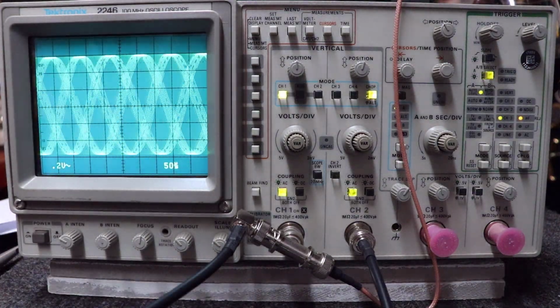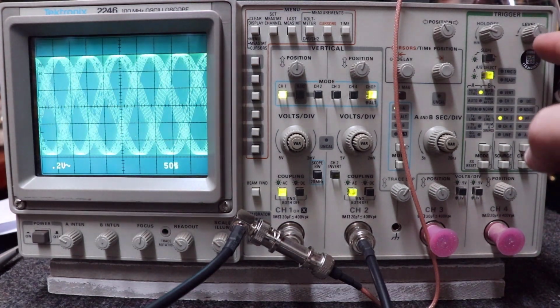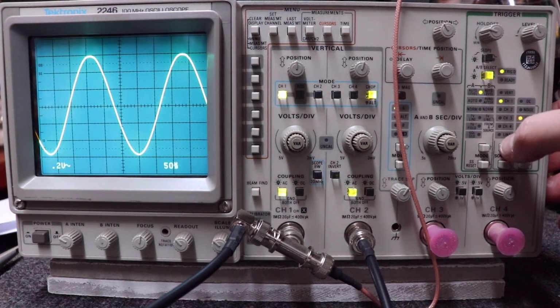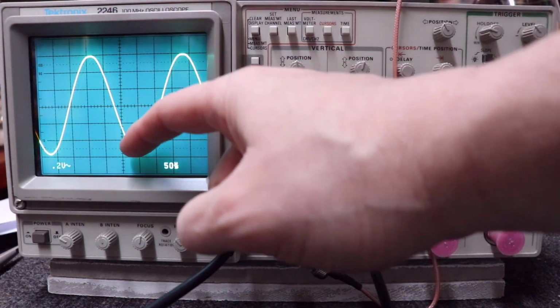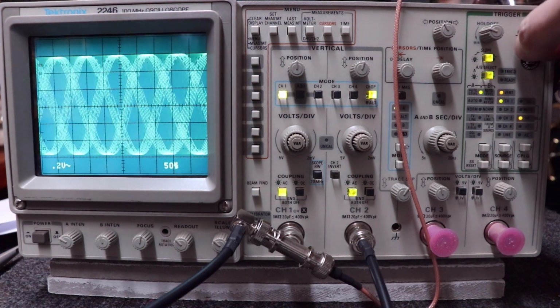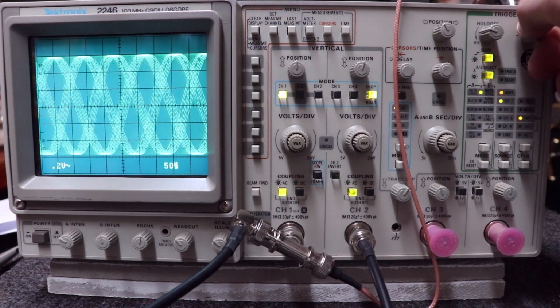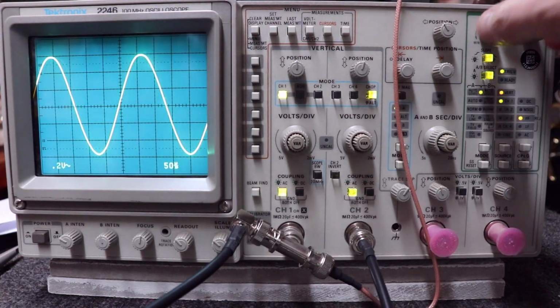So you want to pick the waveform that you want to trigger on, and you've got a knob here that's called level. With the level, you're basically adjusting where on the upswing, if you've got it illuminated there, you're adjusting. See, notice how I got it swinging off? So that trigger determines the level of where you slope.